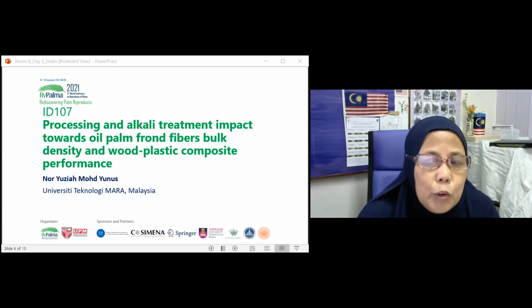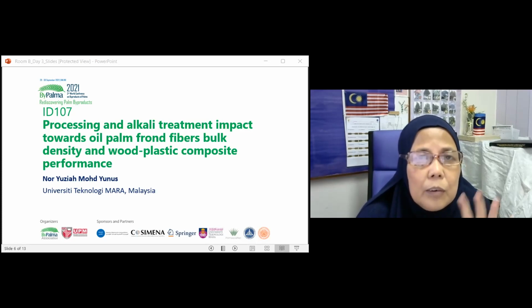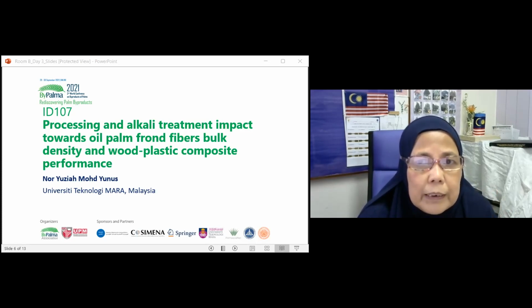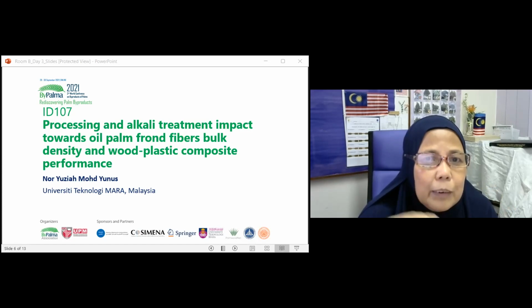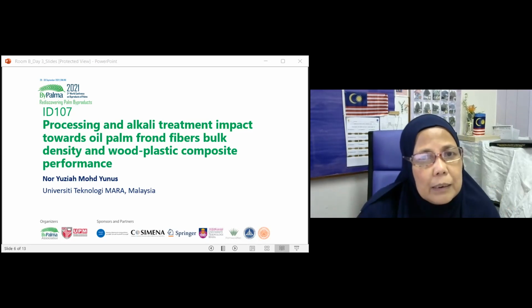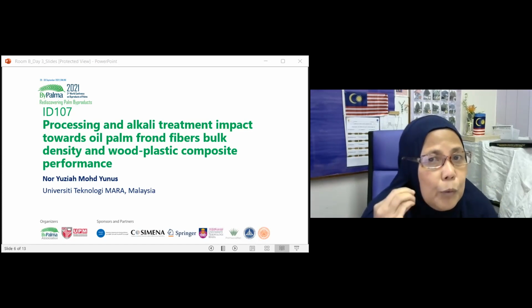The one that is being used here, we are using a melt flow index of 12. Normally, if you want to do normal blending, where you are not going to do radiation and so on, you go for between 12 to 15. The reason is that if you have a very good Brabender machine, you can deal with something with lower melt flow index. Because first you see it melting, but the moment the fiber hits, the torque will shoot up. Even if you start with a torque that is 10, it will shoot up to something like 100, 150. So you have to be very careful on that one.